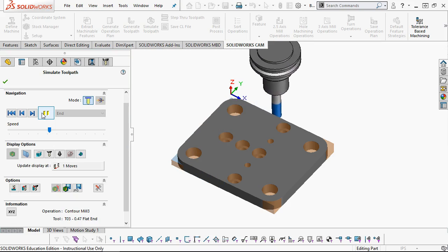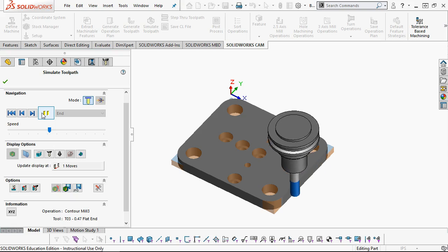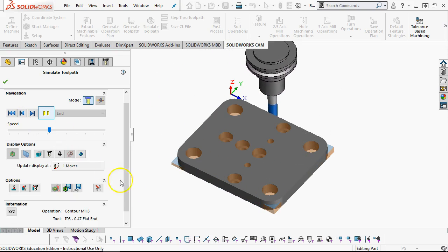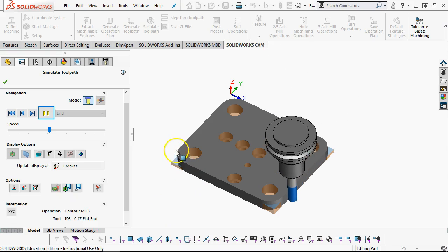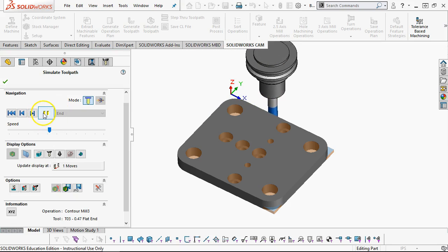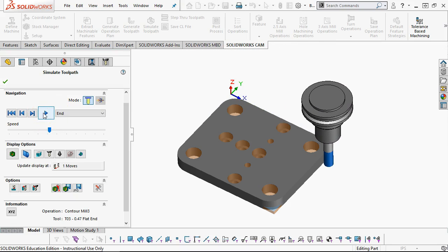And then, we have a step and repeat, so that would mean that I also need a finish pass. Since it's taking multiple steps down, if I don't, I'm going to leave that parting line. All right, so in effect, that first operation is establishing flatness.